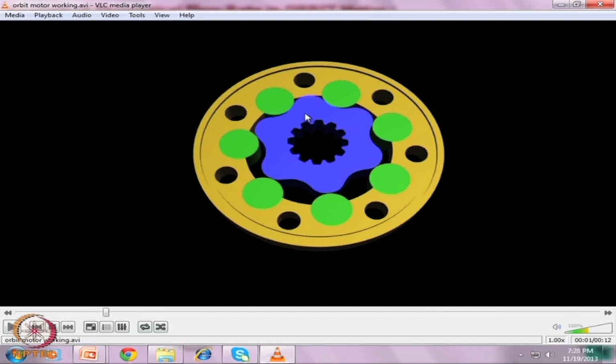Now, the other part of the envelope is that the circle on which these rollers are kept, on the outer body, is slightly less than the pitch circle, so the roller does not come out, and it is selected on the basis of the topmost position of this roller.